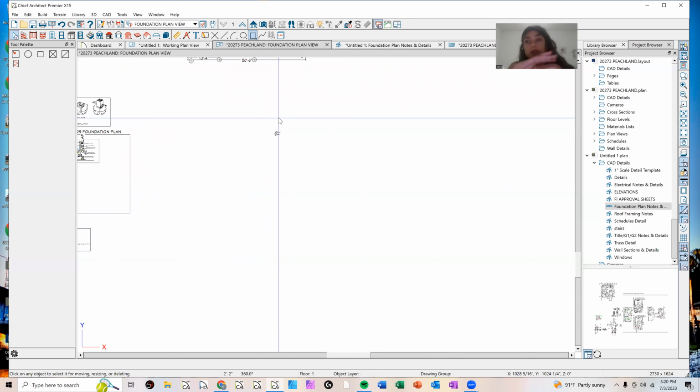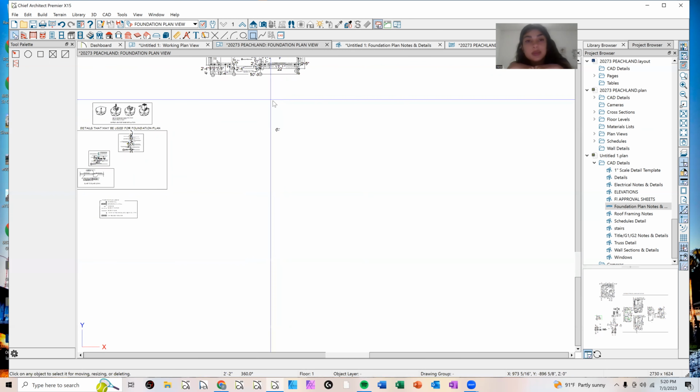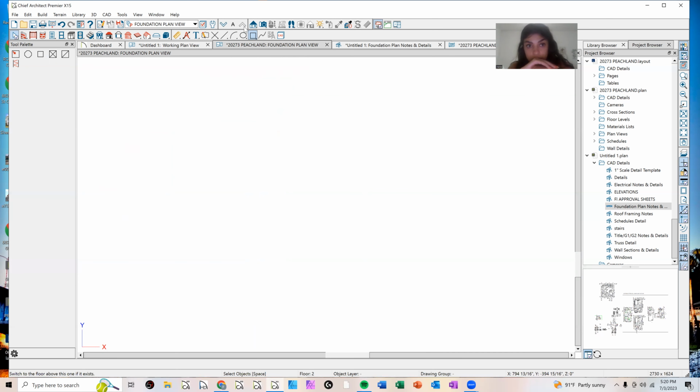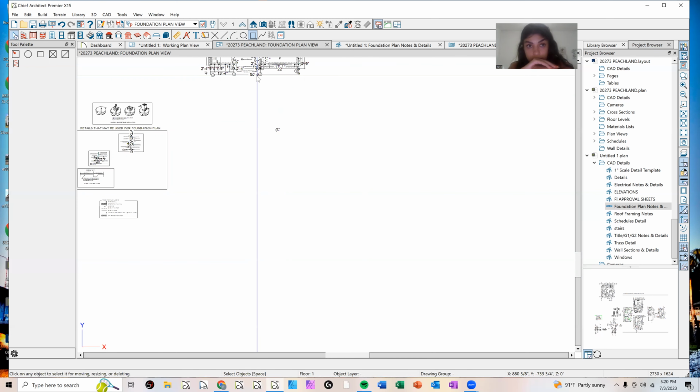About the foundation plan, whenever we're drawing the second floor, we're just going to near the step bottom and press it to say we're doing the top floor or down floor. And how about the foundation? So the foundation plan, you're never going to have a second story, because you're only drawing the concrete of the house, right? The only time you would have a second story foundation plan is if they were running concrete blocks all the way up 2 stories.